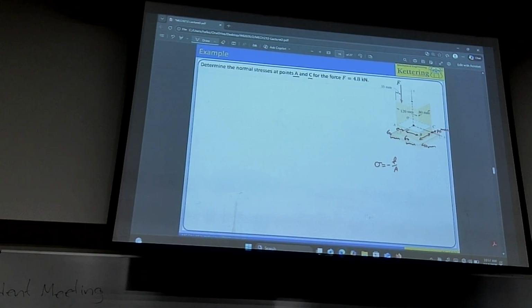So when you say bending, ask yourself this question: does it bend about any of the axes? Yes. First, visualize this. It bends about X like this. Therefore, put MC over I about that axis. So plus minus MC over I about that axis. Parentheses, subscript X. And it turns out there is bending about Z also.